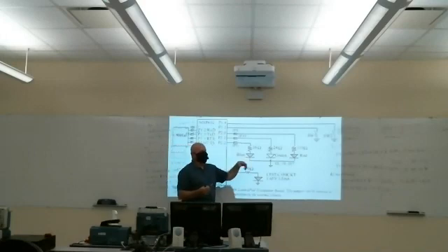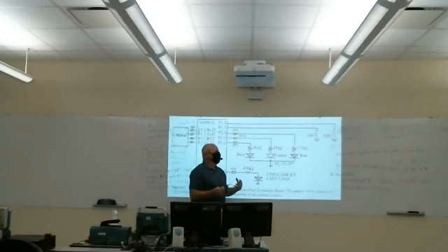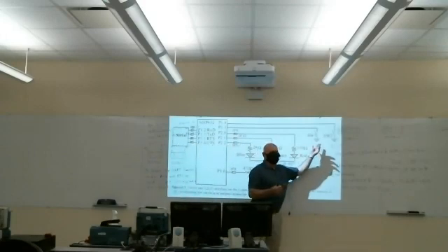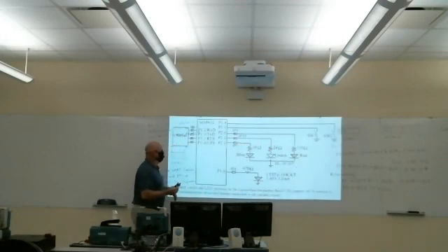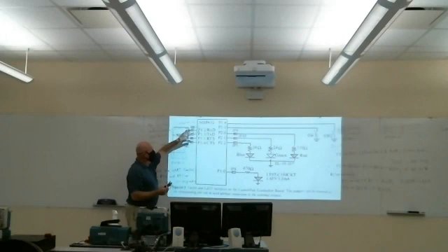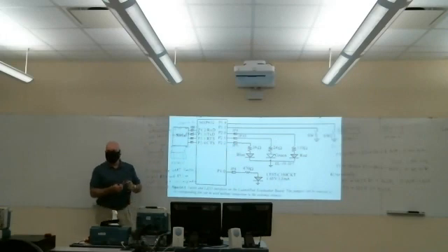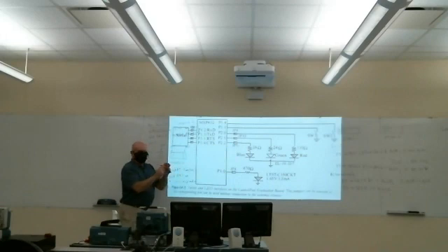Notice that there's no jumper to disconnect the switches. The switches are disconnected as long as you don't press them, so you could use those for something else as well. There are also 4 port pins that are used for the serial interface, this USB serial interface to the debugger chip. And you can disconnect those jumpers.